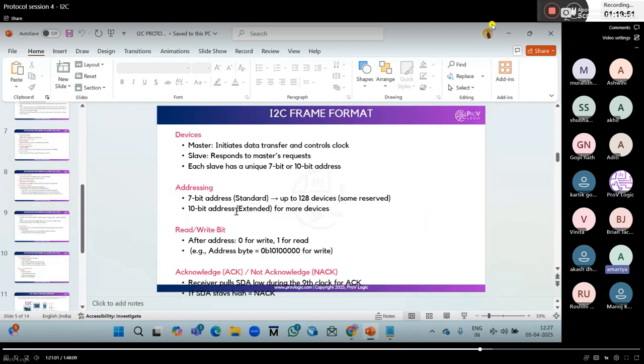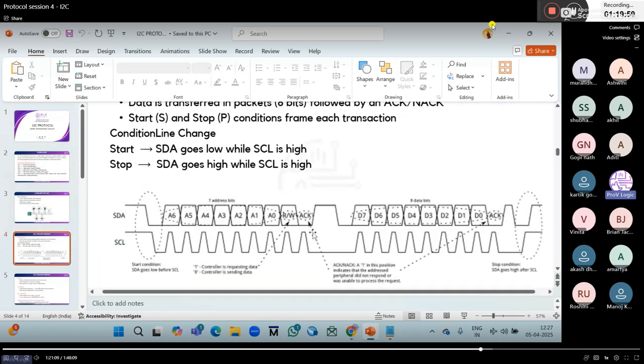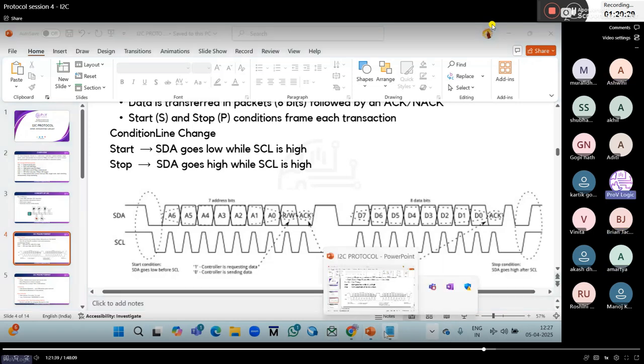Write is completed. We are in the acknowledgement state now. So which state will it go to once write is completed? Start state. Correct? Start state, okay. In which case, if acknowledgement is 0, okay. If acknowledgement is 1, it has to wait for the correct data. Okay. Any other answers? Others?